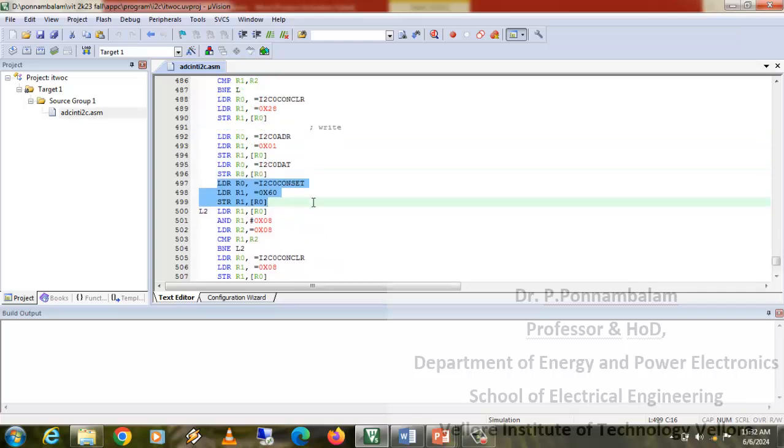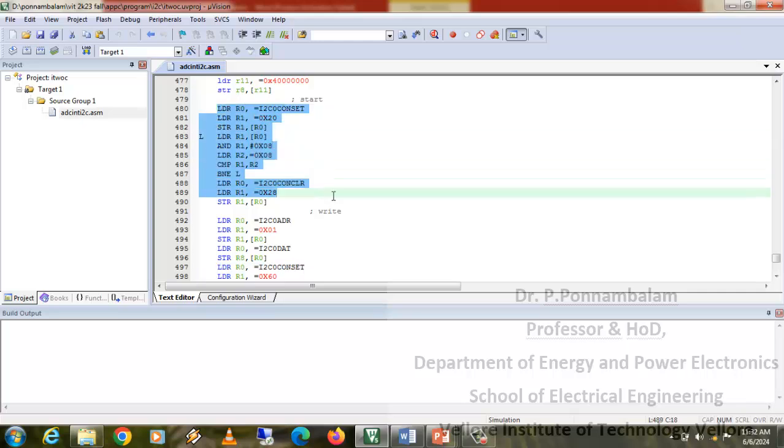Actually this part is to take control of the I2C. I2C works in such a way that your present microcontroller has to go into bus arbitration and take the control when the I2C is free. When the I2C is doing some other communication with another master, this cannot happen. To do that, the SI bit is checked here.